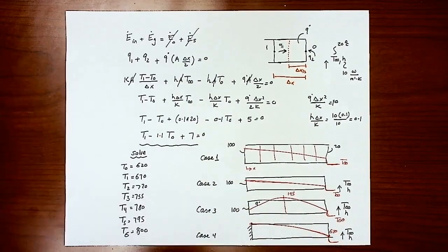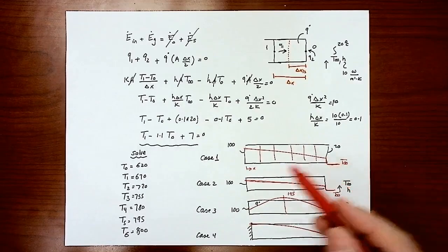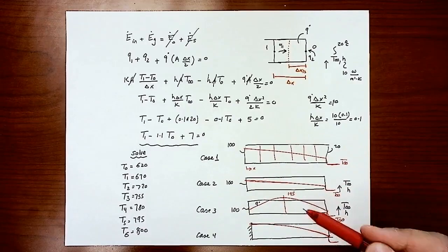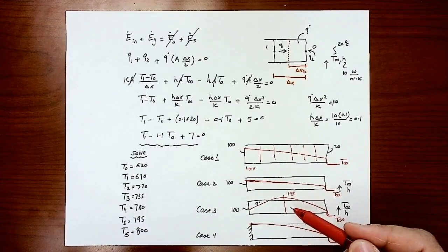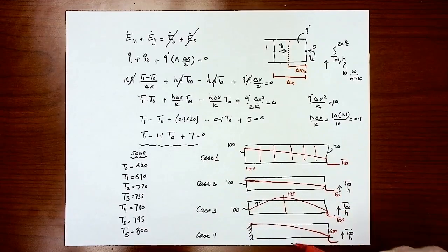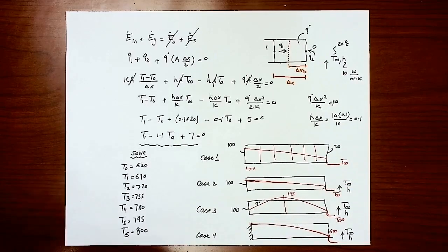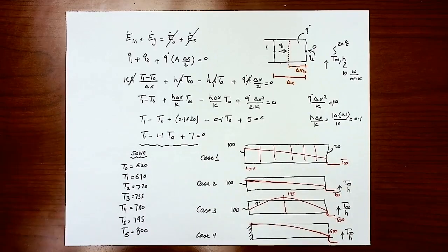And by the way, for all these cases, the analytical solution is available. You can solve the Laplace equation in one dimension without heat generation in the first two cases, with just different boundary conditions, or with heat generation with a different boundary condition here. This is the case where the isolated boundary is present, and this is where the maximum temperature will come. So you can do the analytical solution for all these cases. So that concludes the most common cases that we may get exposed to.